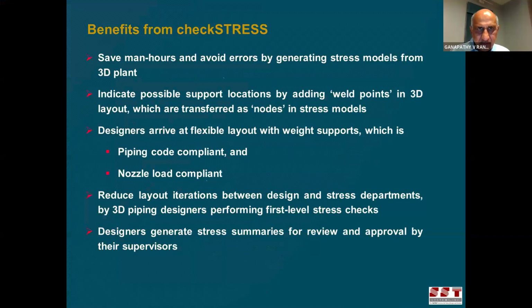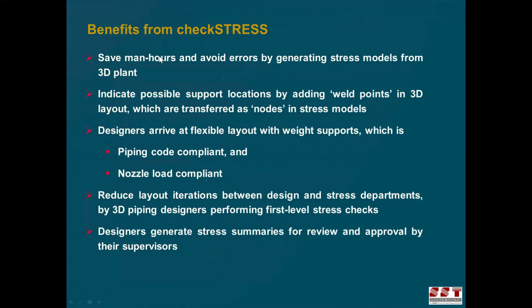Yes. Like Dr. Ranjan said during his presentation, by using checkSTRESS, what are the benefits you achieve? One is you save a lot of man errors and avoid human errors because you're generating a model directly from the 3D plant design system. Then, as I was showing you, in case you want to add the possible support locations for the stress engineers to know, you can create weld points. You just saw that. And those go as nodes in the stress model. That means the stress engineer's job becomes easier rather than going back and forth and reading all the drawings, 3D systems and all that. He doesn't have to do that.